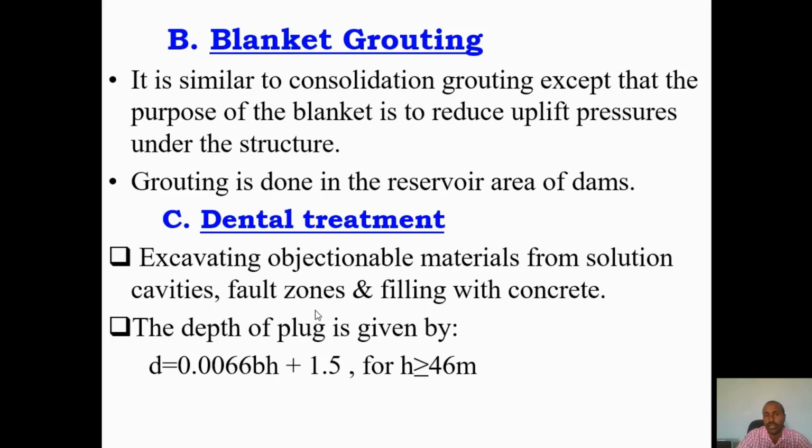And the third one is dental treatment. Dental treatment is just excavation of weak zones and disposing of the material in another place. Simply excavating objectionable materials from solution cavities and fault zones, and filling with concrete. You will fill with concrete. So you excavate the weak zone, you remove it, then fill with concrete.